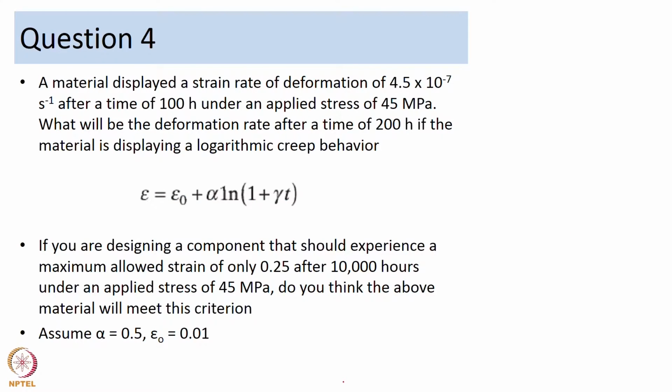So, that is the solution to this problem. Okay, let us look at question 4, or problem 4. This question relates to logarithmic creep behavior. Here we are talking about a material that is displaying a strain rate of deformation of 4.5 into 10 to the power minus 7 per second after a time of 100 hours under an applied stress of 45 MPa.